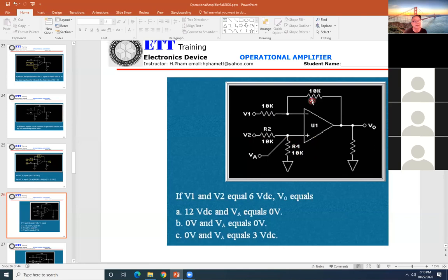The gain is -1. Come on. Sorry, right now I'm using V2. I'm sorry, so it will be 1 plus RF divided by R1. That means gain equals 2. 2 times 3 is 6 volt. So you get negative 6 volt and positive 6 volt. Output will be 0.